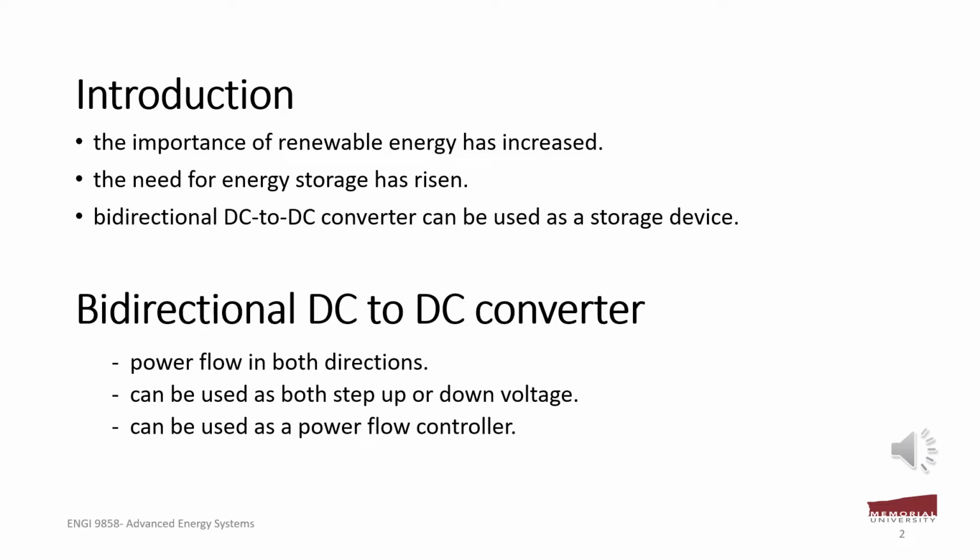In industrial applications also, bidirectional DC to DC converters are used in many applications because devices are switched on and off at high frequency. So, the dual active bridge isolated bidirectional DC to DC converter provides galvanic isolation, storage of surplus energy, and efficient flow of power without wasting energy. For a proper understanding of hybrid energy systems and electric vehicles, it's necessary to have knowledge of the working principle of DC to DC converters.